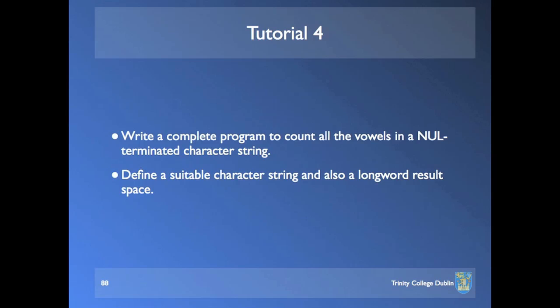Okay, so this is a way of using 16-bit multiply to do 32-bit multiplication, combined in long multiplication. The classic way to implement multiplication on a machine that has no multiplication instructions at all is a combination of repeated shifting and adding. Okay? And one of you, at least one of you, implemented that in assembly language. Used shift instructions and add instructions, or possibly rotate instructions and add instructions, and wrote a program to emulate that in assembly language code.